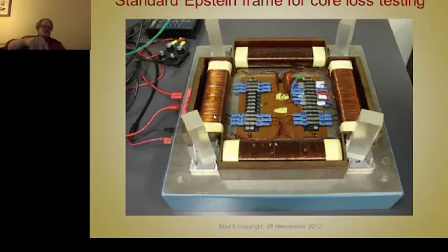So they can adjust the flux density by the current, because they know how many turns there are. So you can adjust the flux density in each one of these by the fixed number of turns times the current, and because they know what the cross section is. They measure the cross section, and so they know how many ampere turns it takes to get different flux densities.